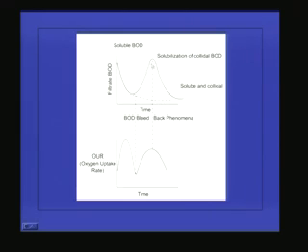And again here is a peak for the BOD. So again the oxygen uptake rate will increase and then come down. If you want to go for a conventional aeration tank or conventional activated sludge process, we have to provide this much time for the complete treatment of the waste, and we will be aerating it continuously. So here the oxygen will be utilized, and here whatever oxygen we are supplying will not be utilized because the oxygen requirement is very low, and again here we are utilizing the oxygen.